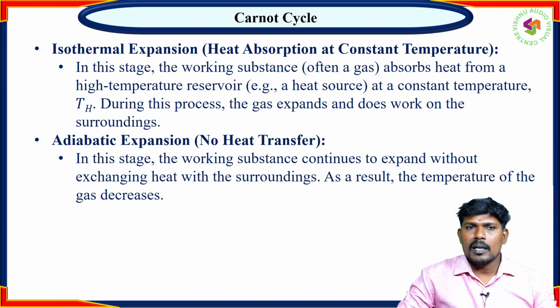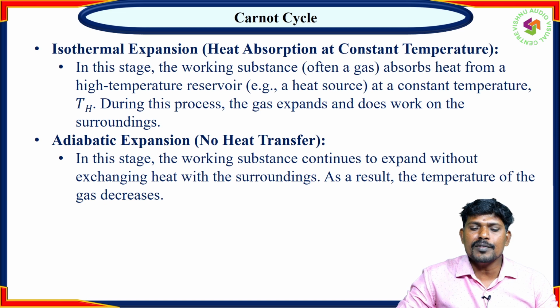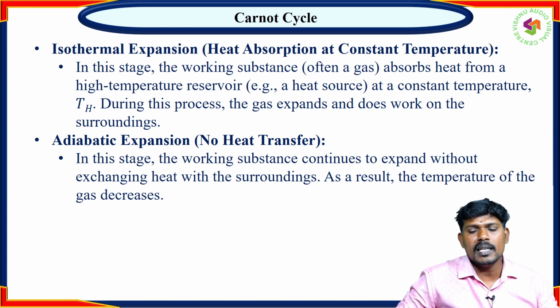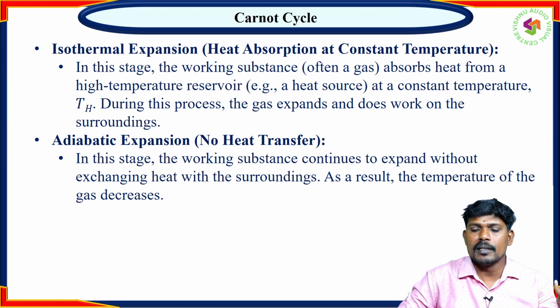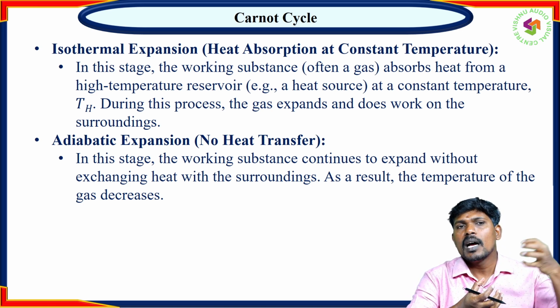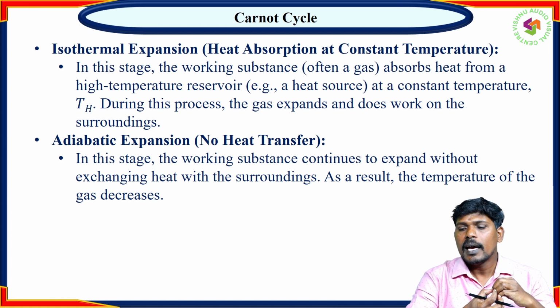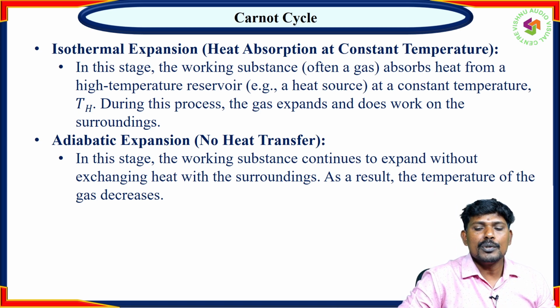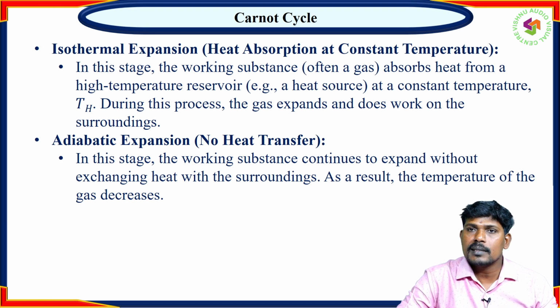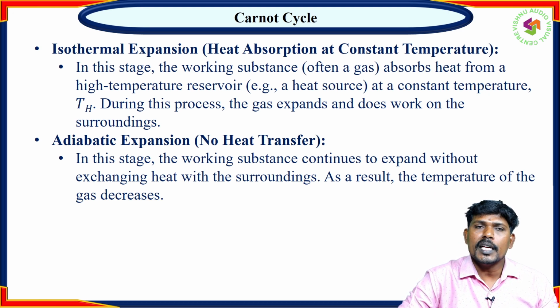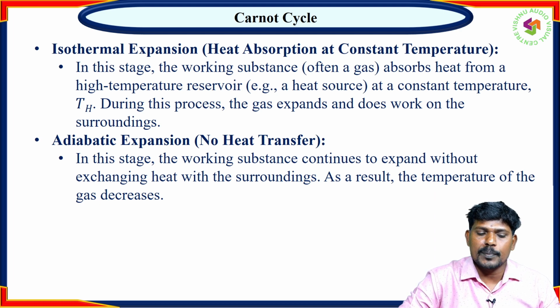So these are the four stages. First, isothermal expansion. In this stage, the working substance, often a gas, absorbs heat from a high temperature reservoir. The high temperature reservoir is the fuel. The gas absorbs the heat from the fuel at constant temperature, that is TH. During this process, the gas expands and does work on the surroundings.